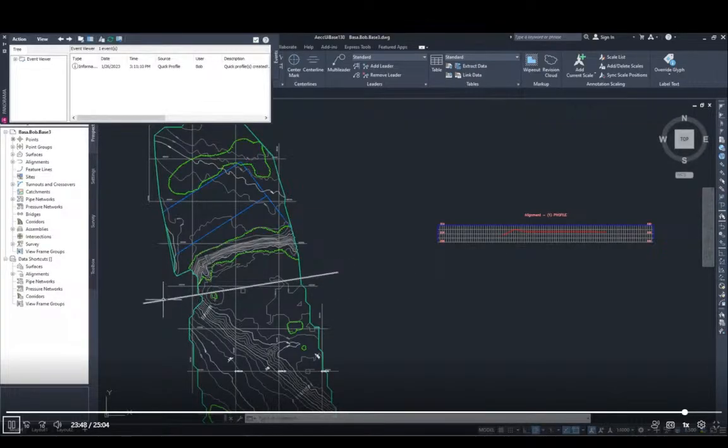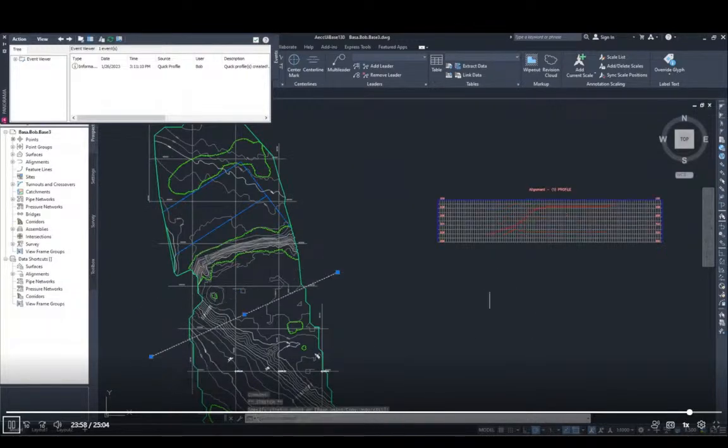And this is dynamic. So this is just to demonstrate some purposes here. If I click the line and move it here, you can see it's crossing different contours now down here. If I click it there, look at that now, you see? On the left, we go up a lot of contours. We're gaining a lot of elevation here, and then it settles down over here, and that's reflected here in the red line drawing. You can play with this a little bit, right? You can just move these, see here, and that one looks like that. So that gives us a quick profile right there of that, right?